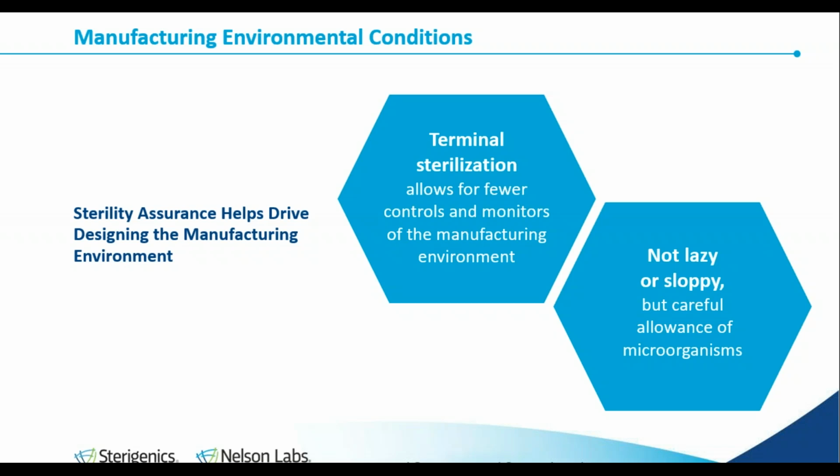But certainly, if terminal sterilization is in place, then you are permitted strategic reduction in these controls and monitors in the entire process to allow for the presence of microorganisms in a controlled fashion, just knowing that the terminal sterilization, the intent there, and the validation you perform will account for those.